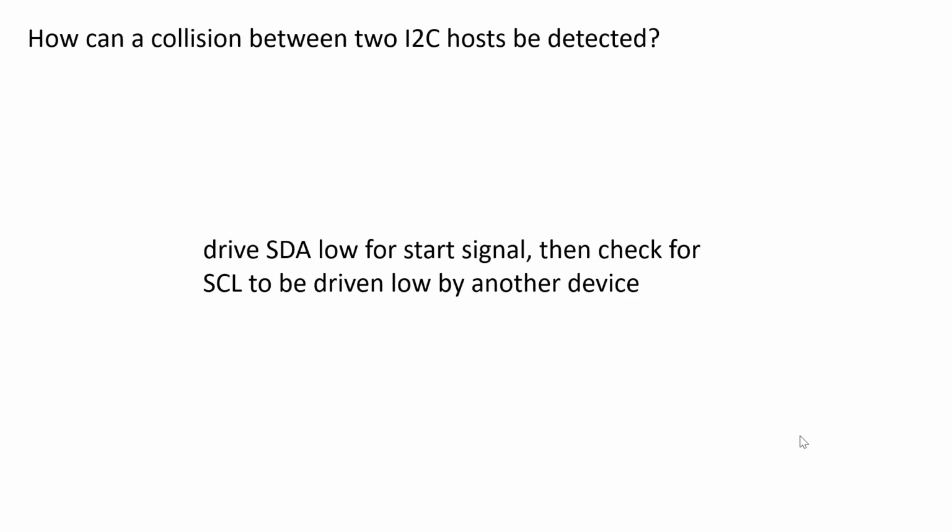This one, I'm not sure if this is exactly how it works. This is just a possibility. But if I am trying to take control, take mastership, and I initiate a start bit, so I'm going to drive SDA low first, right? Then you have to wait to see if something else is cycling the clock, because a host is the only thing that can cycle the clock. Yeah, exactly. So I think the presumption here is that we have a collision, but I am the one that's slightly behind the other one.